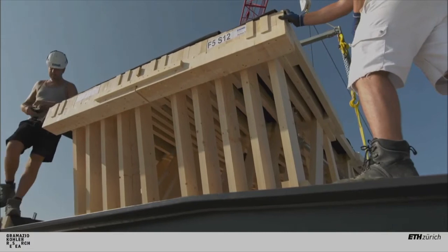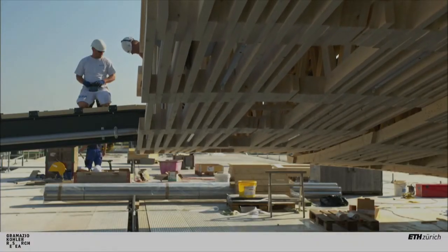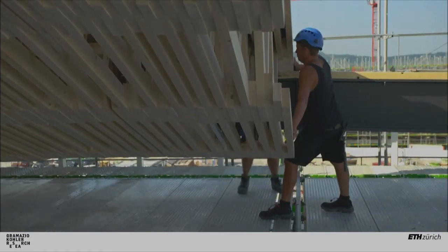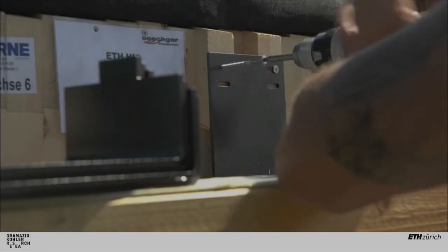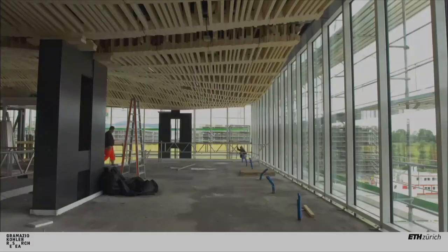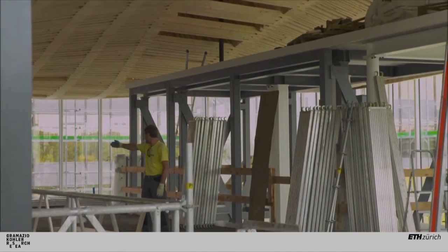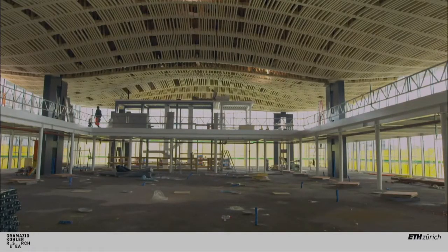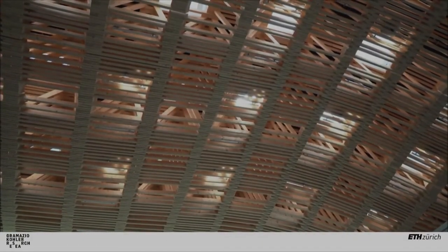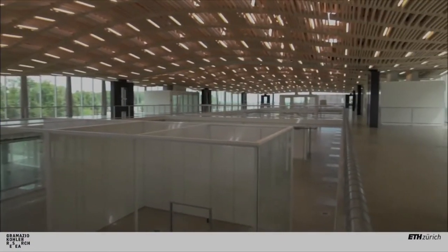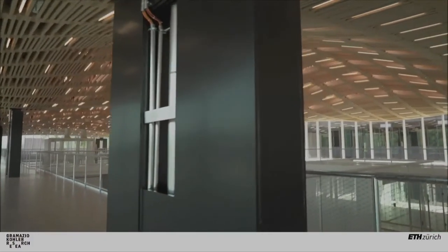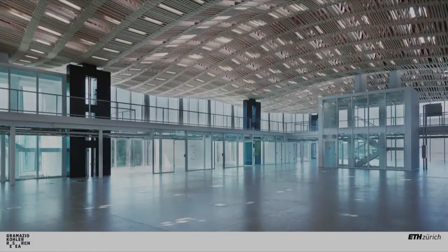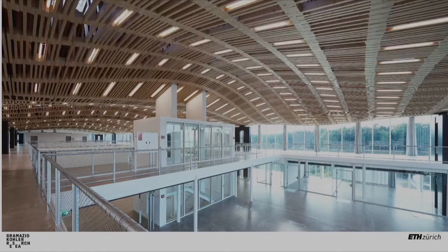So the complexity of organizing 50,000 slats of this size, with no identical geometries, gets simplified on the building site to the placement of 168 trusses. They just have to go in the right place, and then it's fine. And all this complexity, I said 50,000 slats, but this means 1 million nails. And given that there is no identical connection, the angle is always different. The overlap area is always different. So the position of the nails and the amount of nails, which depends on the connection and on the structural conditions of the connection, are always different. Here you see the result.